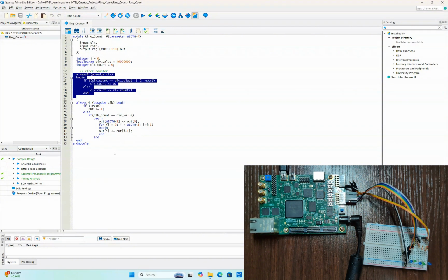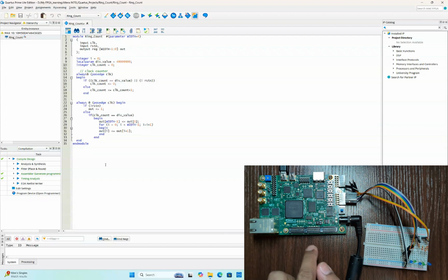So you can also see the hardware in the sub window. Here the hardware is also a bit different. In our previous videos, we mainly used the LEDs on board. For example, we used these LEDs, but we discussed that these LEDs have some issue. It's not an issue, but they are connected active low, which means whenever you are giving a high signal, or whenever you are asking it to turn on, it is actually turning off. So to solve that, we use an inverter.